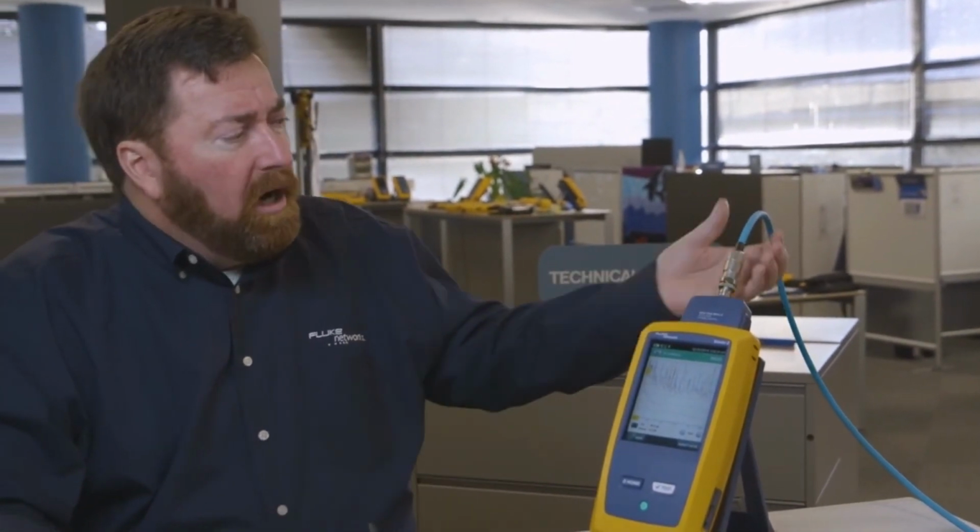Now, we are using a shielded cable, so the shielded cable should eliminate any of that external noise from getting in. And we'll find in the ISO world an open discussion about whether or not, well, it's not much of a discussion, in the ISO world, if you have a shield, you're not required to run these TCL tests. All right, so we've seen in the 1005 test that we have some tests that include the TCL values and some that do not. As we get into a tougher environment, we may be interested in using the more stringent tests, the E2 or the E3 tests.